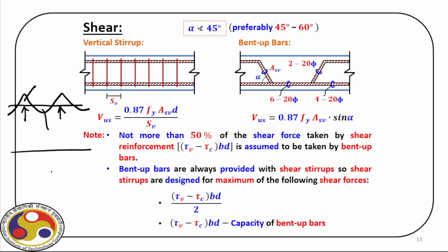So if we see the main reinforcement, obviously at the middle we have these bars, while when we go over the support, we have the main reinforcement at the top, because due to hogging bending moment, we have tension at the top, compression at the bottom. Now to have this type of reinforcement arrangement, we can have bent up bars. So some of the bars at the bottom can be bent up and brought to this top surface, and that's why we have this kind of situation.